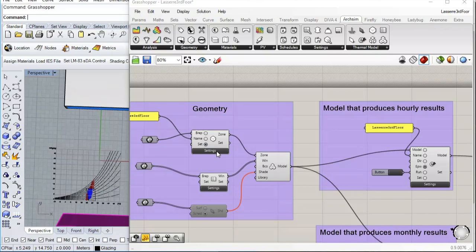And the 2 main ones are the settings related to the building geometry and occupancy patterns and whether there's heating and cooling loads, etc. And the same we need to do for the windows and setting the parameters for the R values for the window, shading, etc.